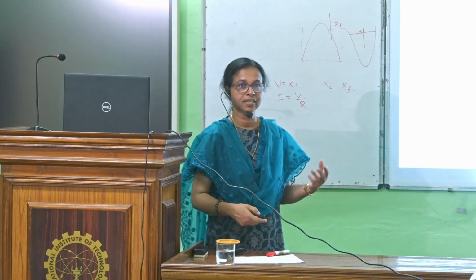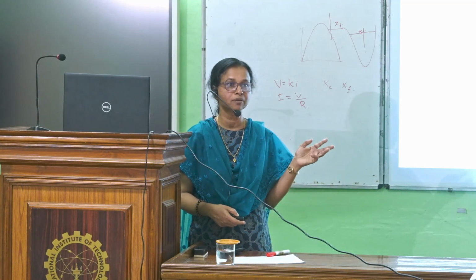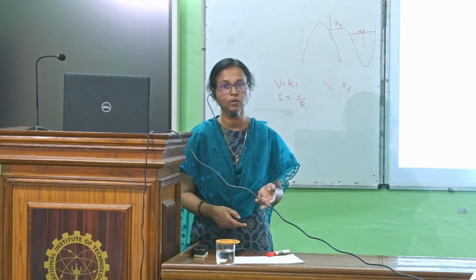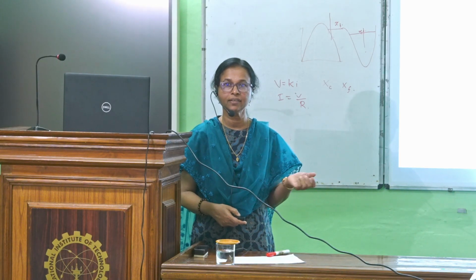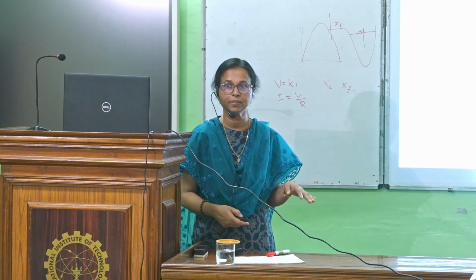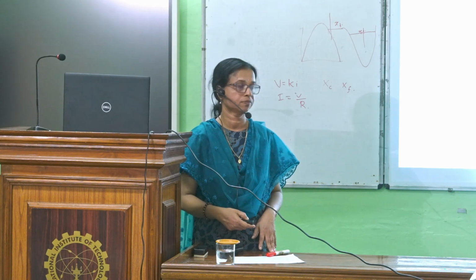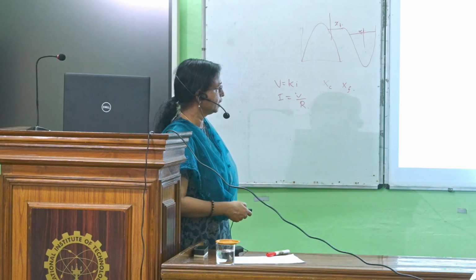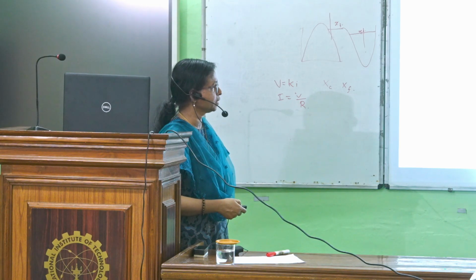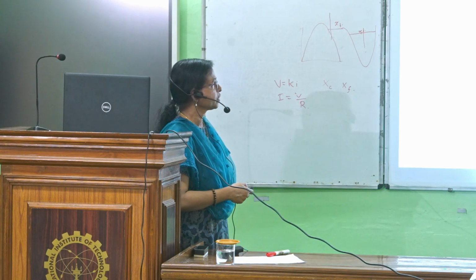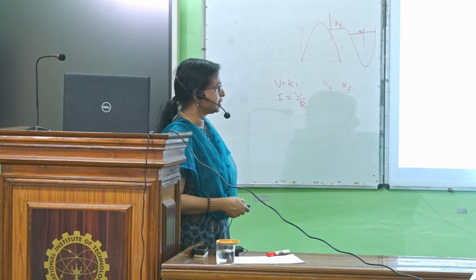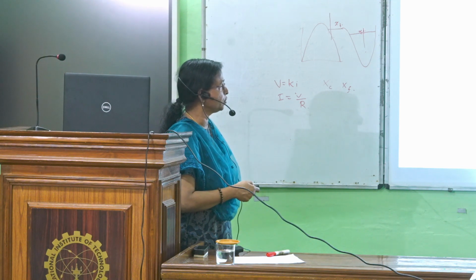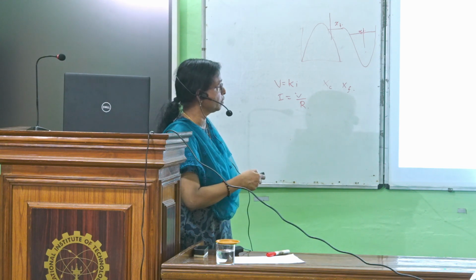Usually this will be taken from the DEM that you are giving, but you can also conduct a survey and give the actual elevation. That will be the better way of finding the cross sectional details. So this is the method: using the standard step method, you can find Y2 by assuming a value of Y2. So the method is to assume a value of Y2.